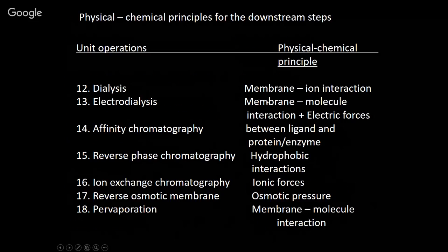Electrodialysis, of course, is also a membrane-based process. We apply an electric field, as the name implies, so the ions move towards the anode or the cathode, depending upon the nature of the charge. We can use electrodialysis for purifying brackish water, salt water, into very pure water. And we can use it for removing salts from a mixture of protein and salt. Alternate compartments will have salt, other compartments will have the pure protein.